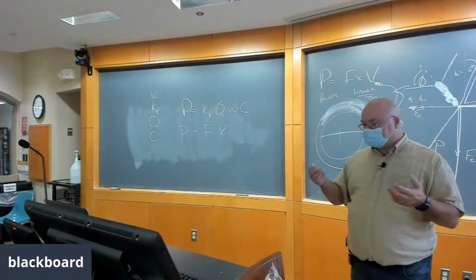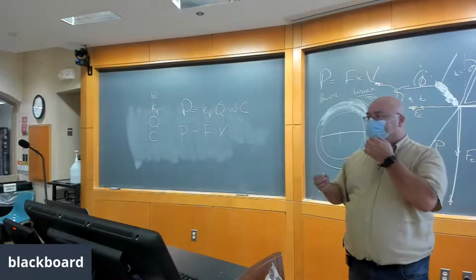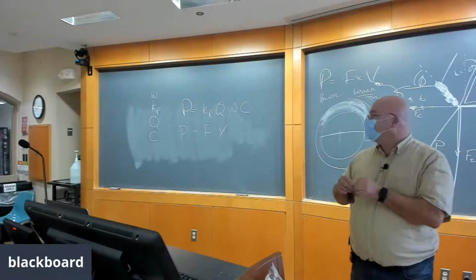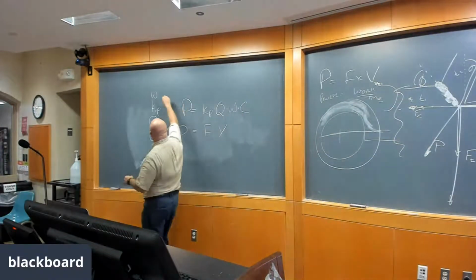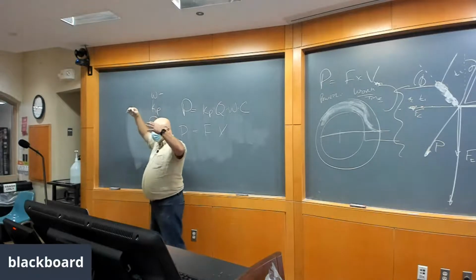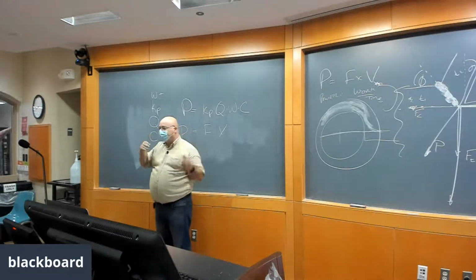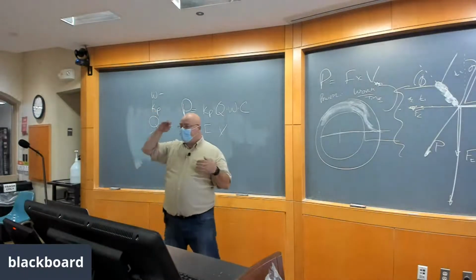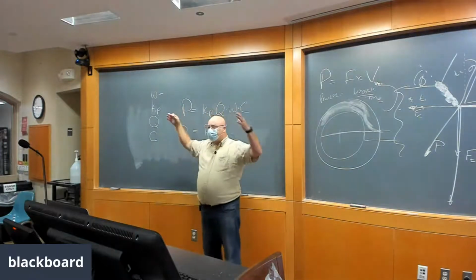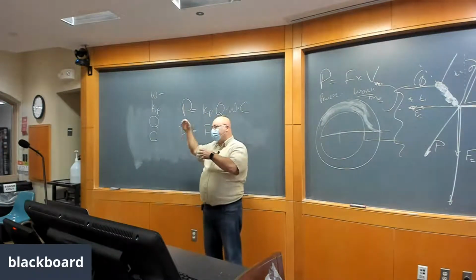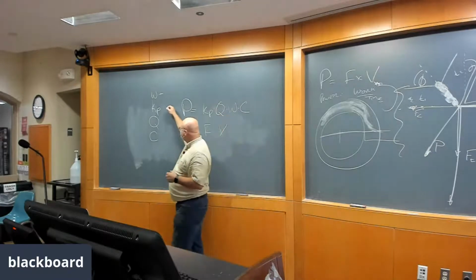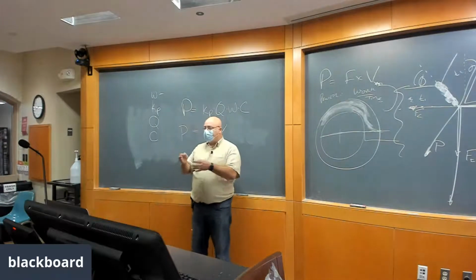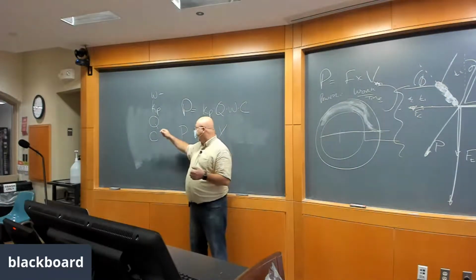Sure. So W is our tool wear factor. So it's basically how sharp is the tool. We looked this up in a table from the machinery's handbook. KP is a machinability factor that has been determined by thousands and thousands of experiments that people have done and written papers about, put the data together to do all this. Our material removal rate is basically the volume of chips you're creating over time. So it's volume over time.